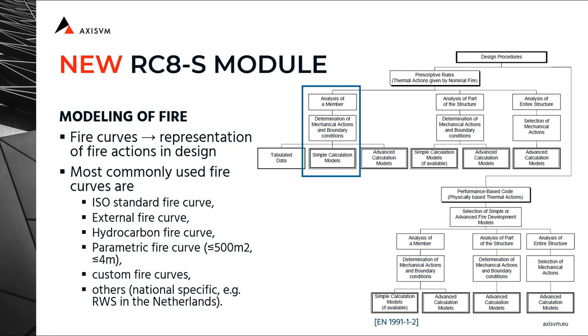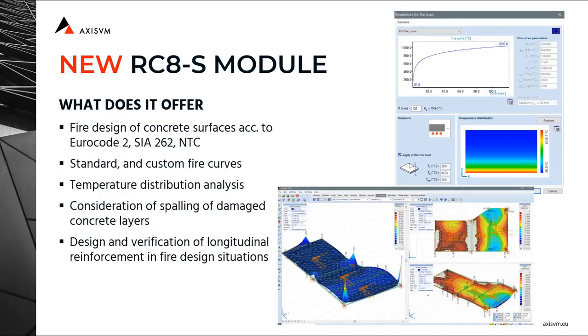All structural fire design modules in AxisVM follow the prescriptive design rules by using fire curves and simplified calculation models. It is also important to note that member analysis can be performed in AxisVM. It means that the fire safety is verified on isolated members. To summarize, RC8S offers a tool for fire design of concrete surfaces according to Eurocode 2, the Swiss SIA 262, and the Dutch NTC standards.